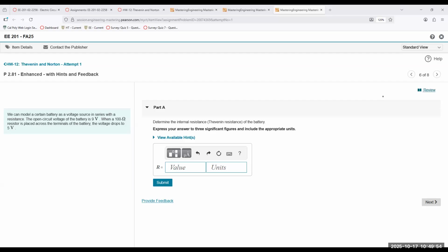Then once you're done with that measurement, you take the terminal out, put it into voltage measurement, and measure VTH. Whatever voltage is coming, it's VTH. It would take you less than 10 seconds to switch and take that measurement. Once that is done, on the left-hand side, you have a voltage source on that circuit.